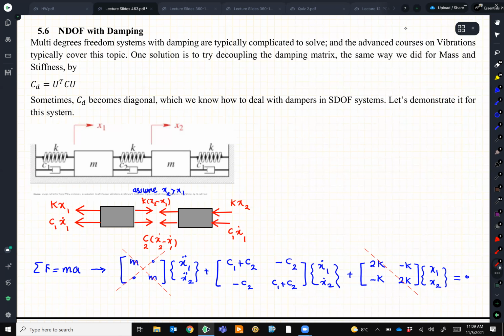The matrix would be non-zero on the off diagonal. With the spring or without? Without the spring, yes. The masses, their accelerations are connected. We have an example, I guess 24, where the masses are connected. Yeah, that's correct. So for the stiffness, the diagonal is the sum of the stiffness, and the off diagonal, with negative sign, is the stiffness between these two variables, as you can see, minus k.